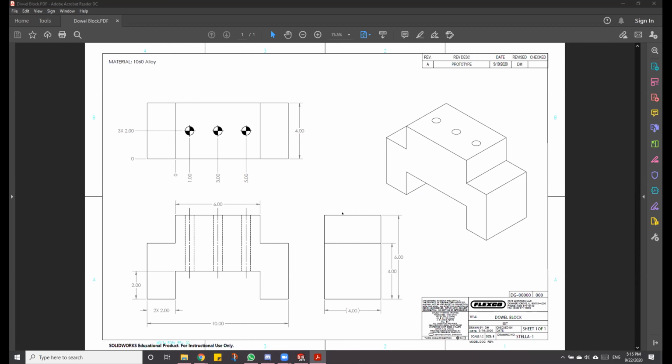Next thing is multiples. So for example here, I have that this block is an overall of 10 inches and that each of these little leg sections is 2 inches. I don't have a dimension for the center because that would just be redundant. I already told you how much this is and how much this is. You can do the math. Because if I add a dimension, it messes with the tolerances. And I'll show you why.